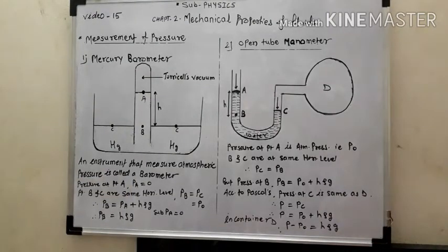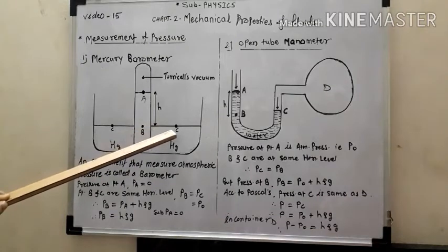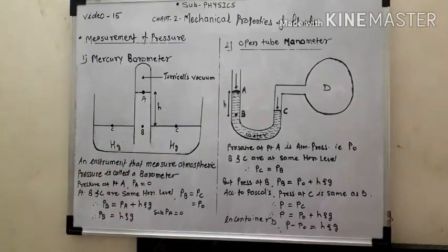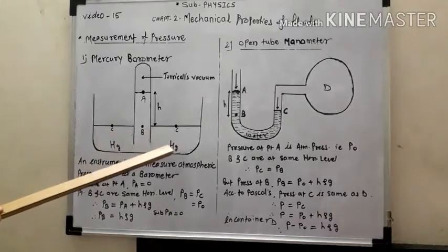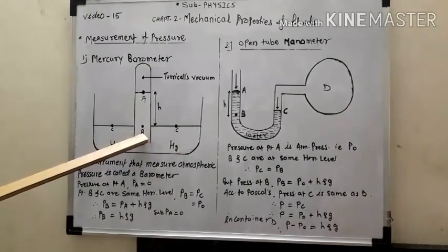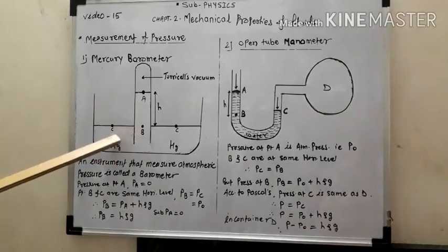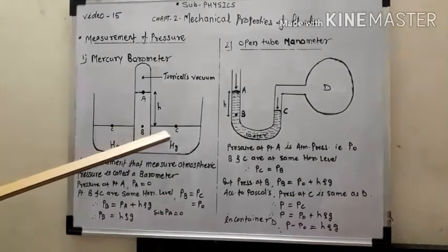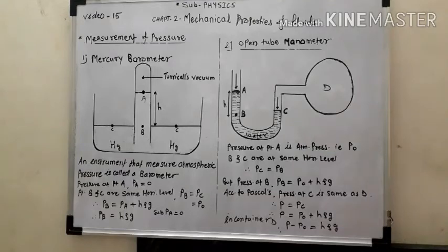Now the pressure at the upper end of the mercury column inside the tube is 0. Therefore we can write Pa equal to 0. Let us consider the point C, which is on the mercury surface in the dish, and another point B, which is inside the tube at the same horizontal level as point C, so that the pressure at C is equal to atmospheric pressure.